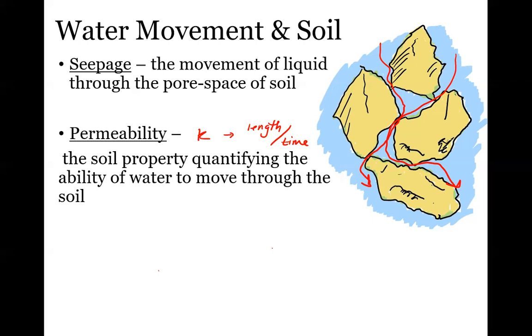Yes, there's a term called hydraulic conductivity that's often associated with permeability. Hydraulic conductivity is normally the term used by hydrogeologic engineers, because we're talking specifically about water. But permeability is a broad term for a specific type of liquid that has a set viscosity. So natural gas has a permeability through rock. Bitumen has a specific permeability. That permeability coefficient is going to be dependent on the viscosity of the liquid, which we'll see in the labs coming up.